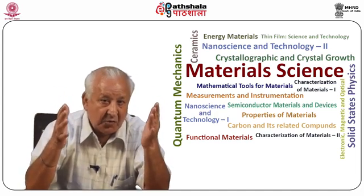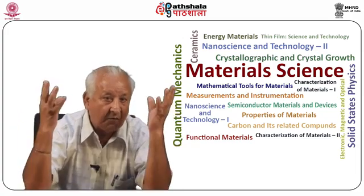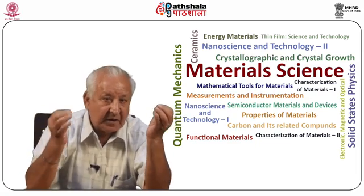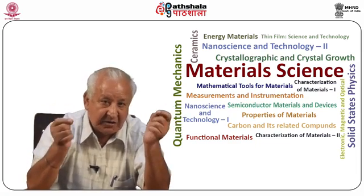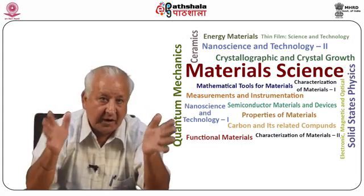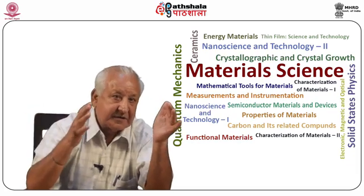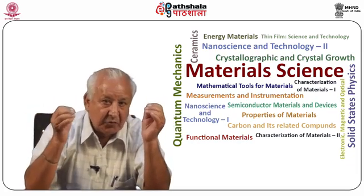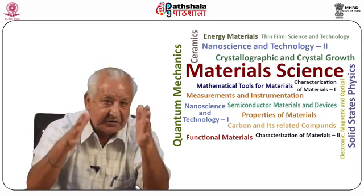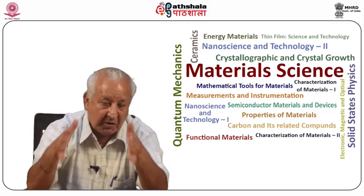The material to be grown as crystal is placed in a long boat with dimensions of 1 foot in length and 1 inch in diameter so that it is completely filled. Then a section of the material is melted with the help of narrow heating coils. The molten material is now traversed along the boat by moving either the boat or the heating coil. As heating coil proceeds, the material melts, leaving material behind it to solidify.